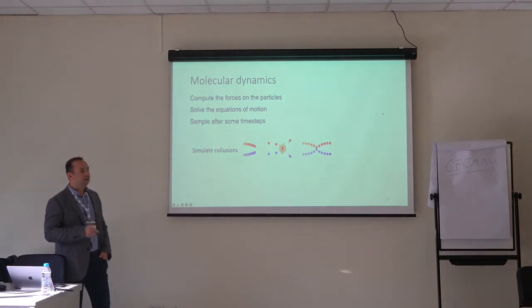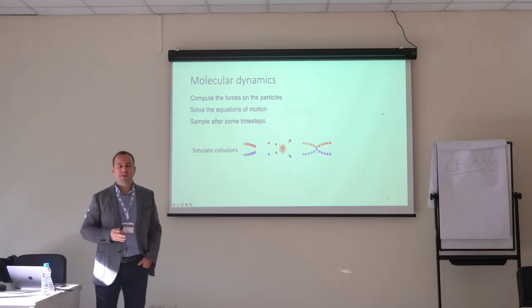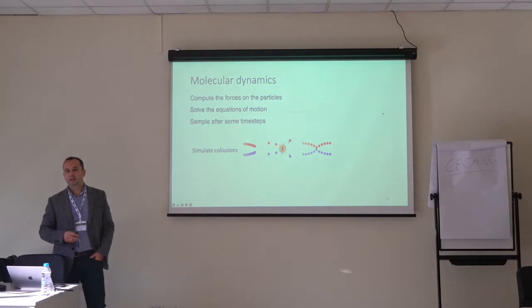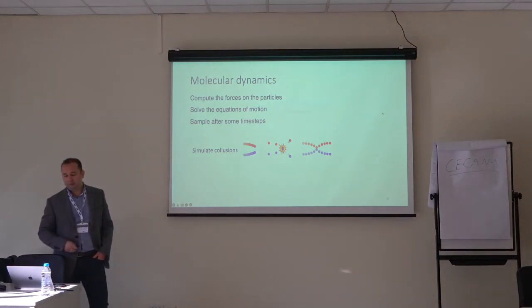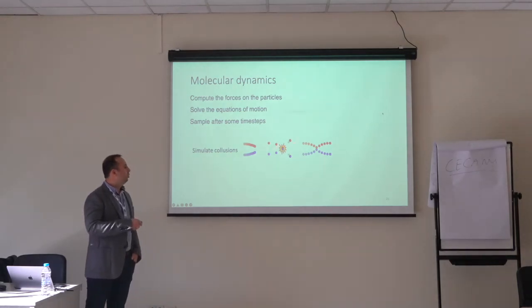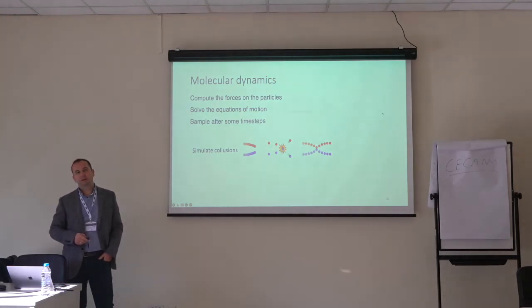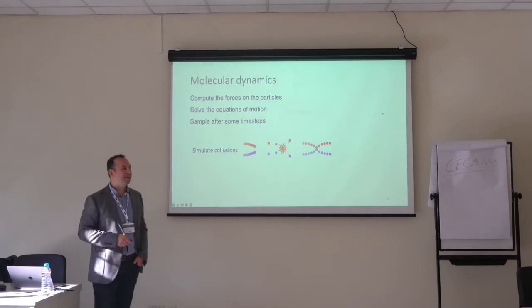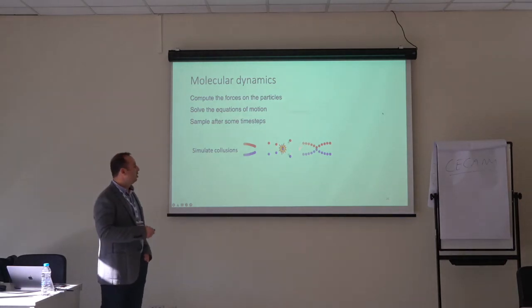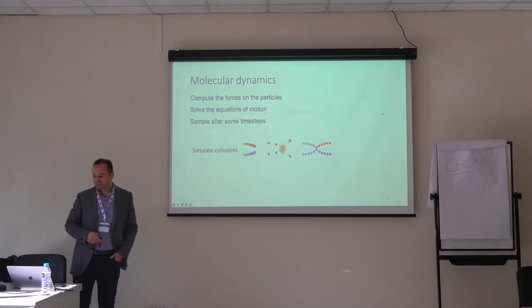If you discretize your whole simulation time into smaller time steps, and you take it too small, then you end up with a low level of integration of time steps. If you make it too big, then you have unrealistic collisions, and you will for sure end up with unbalanced, uncontrolled energy in your system. So you need to take a proper time step in order to model these collisions.